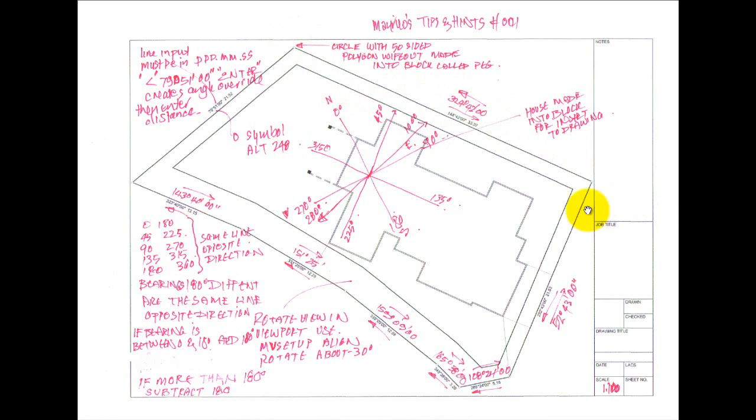From the next one, do the same thing. You want to go in that direction, so 144.42. You'd push the less than symbol, and then 144D 42 minutes 00 seconds. Enter. Make sure you get that angle override message, and then put in the distance. The thing with this is you must make sure, of course, that you have your units set to degrees, minutes and seconds mode, so it understands your input.